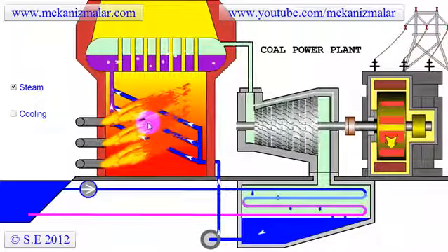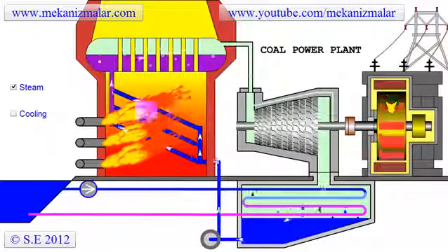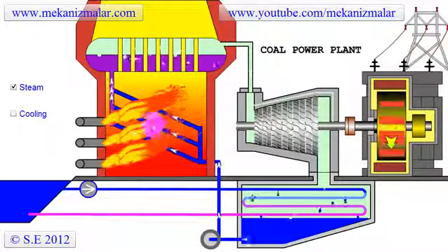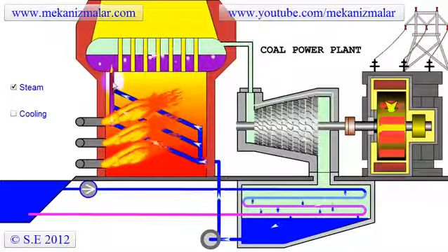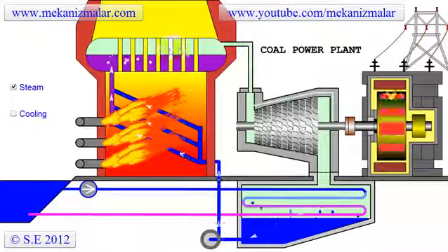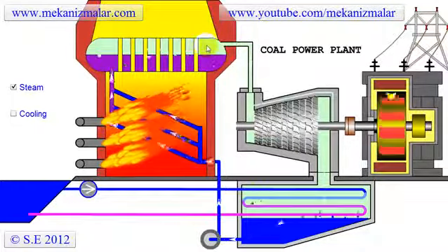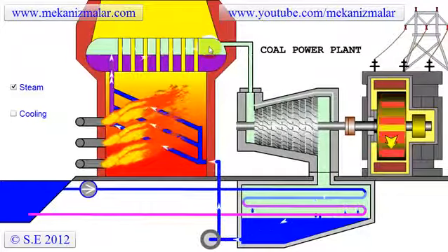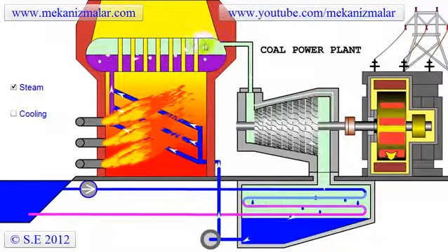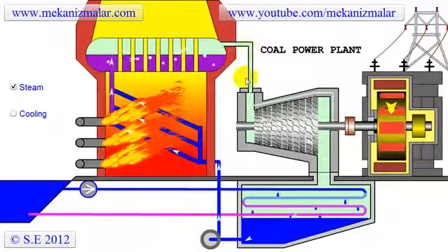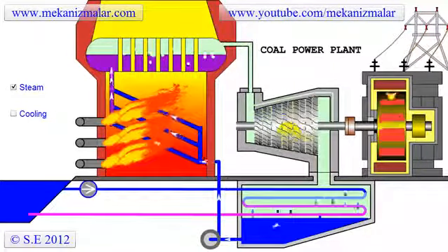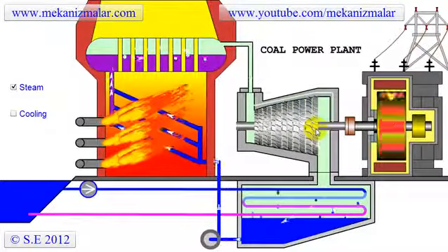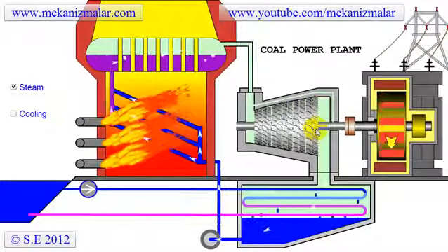First, intense heat inside the furnace heats the water within the coils, which is coming from the condenser. This heated water is forced to the boiler, where it evaporates. The pressure inside the boiler can be more than 200 bars. The high-pressure steam obtained in the boiler is sent to the steam turbine, which passes the steam between fixed and rotating sections, converting the energy stored in the steam to mechanical energy.